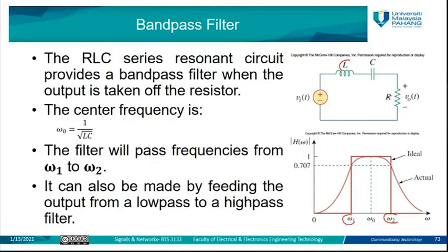So in order to find the transfer function, you also need to write the equation. For example, here you have V in. Your equation will be in this form: V in of S minus VL of S minus VC of S. Why minus? Because this is the only source in our circuit. This is the voltage across the inductor. This is the voltage across the capacitor.